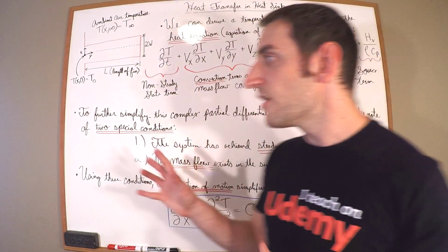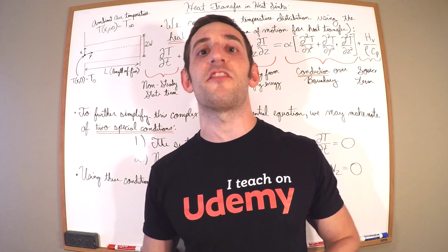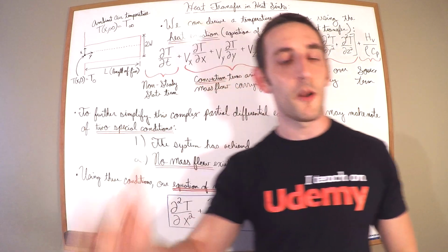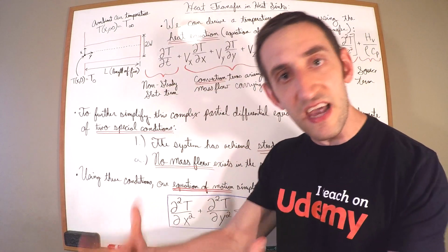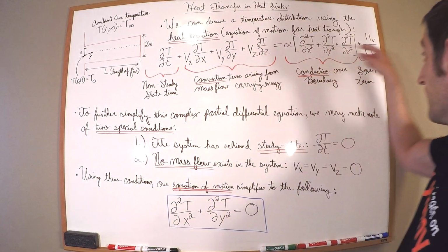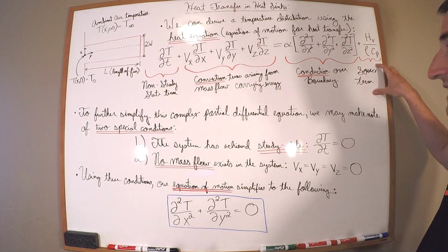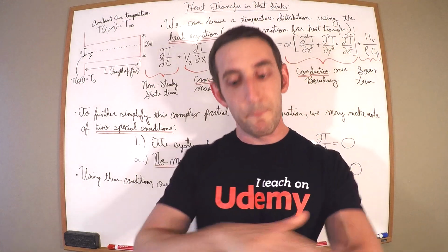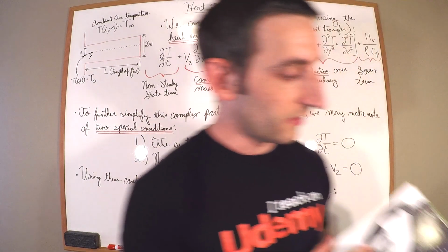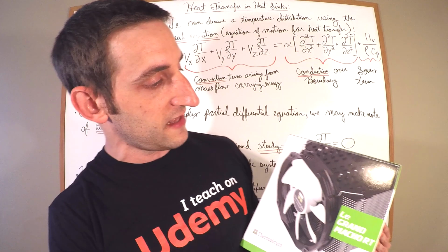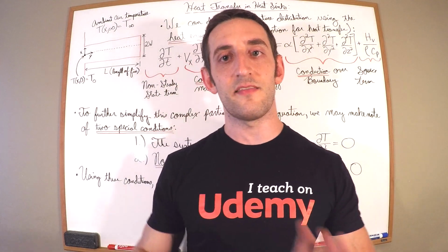So we make note that we're only going to analyze this at steady state, and that makes sense for our situation because you start up your computer, it starts transitioning, right? That CPU does some computation, right? You get this guy generated. This is a source term inside your CPU that generates that heat. It starts warming up the base plate of your heat sink, or maybe the tubes that are running through with all these fins. And then eventually, you're going to start getting this constant temperature.